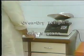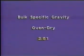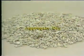The weight of the oven-dried test sample in air is 6,854.5 grams. To calculate for bulk specific gravity, divide the weight of the oven-dry test sample in air, 6,854.5 grams, by the weight of the saturated surface dry sample in air, 6,957 grams, minus the weight of saturated test sample in water, 4,331 grams. The bulk specific gravity, oven-dry, of our test specimen is 2.61. Bulk specific gravity based on the oven-dry weight of the aggregate is used when aggregate is dry or assumed to be dry.